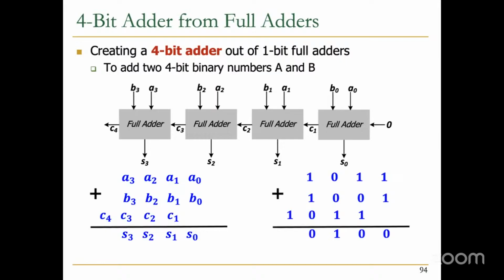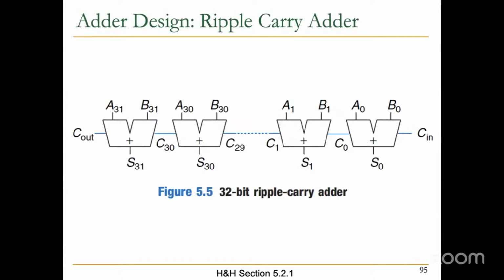Okay, you can convince yourself that it works, which I'm not going to do here. Makes sense, right? This is also called a ripple carry adder. If you heard the term ripple carry, carry is basically rippling across 1-bit adders. This is a very simple adder you can build from 1-bit adders. Now, there's a downside of this adder. Latency, right? Yes, you were going to say that? Okay. Basically, in order to evaluate the last bit, you should have evaluated everything before.